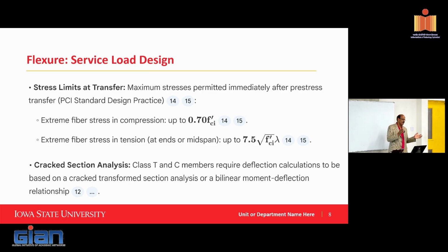So in the transfer situation, if you know that the load is going to be over a short time, that is one thing, and then you can also create micro cracks in the concrete because the concrete is pretty young. So when I say transfer, you're talking about 24 hours or 18 hours old concrete. So you don't want to cause micro cracking in the concrete, and then that will compromise the quality of concrete as well.